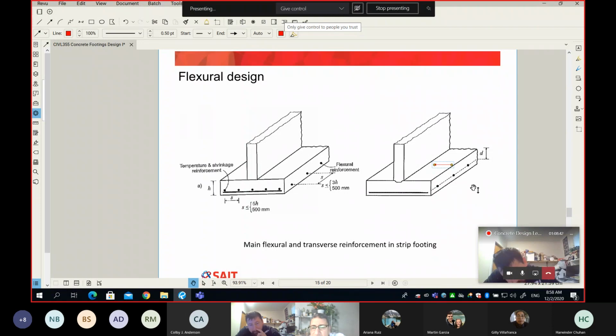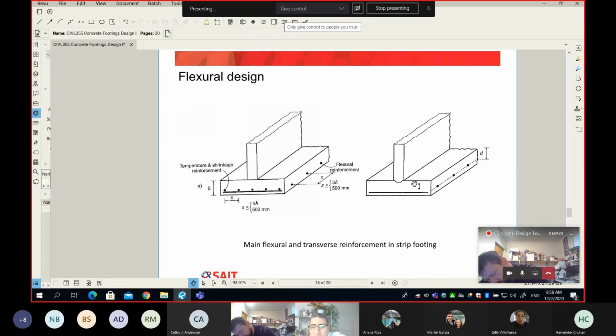The difference is the main direction reinforcement comes from the moment, from the load. For the transverse, there is no load, so we just go ahead and add the minimum reinforcement in the transverse direction, if you guys remember. Let's make it clear. On this picture here, I have a question for you, and actually it cannot be a question because the answer is already on my slide.